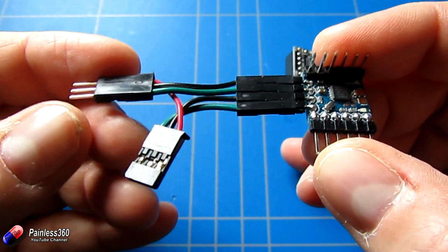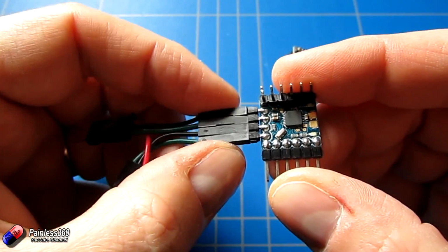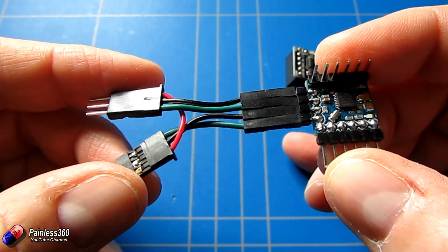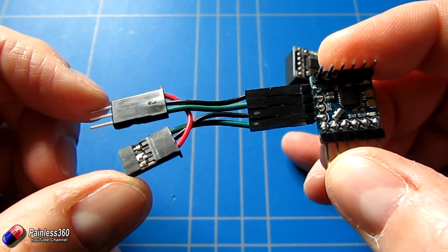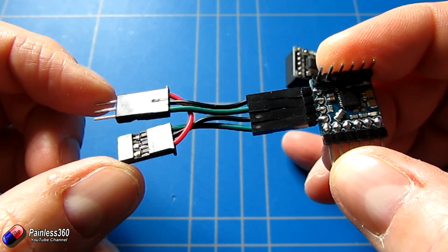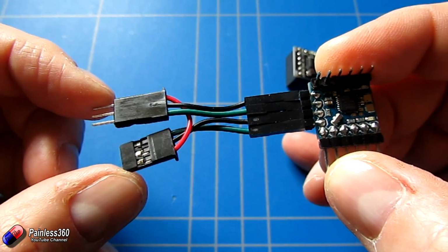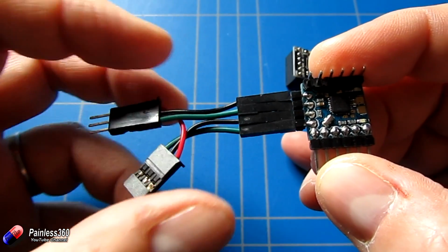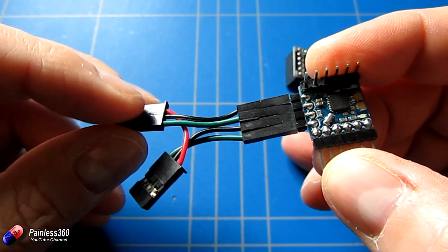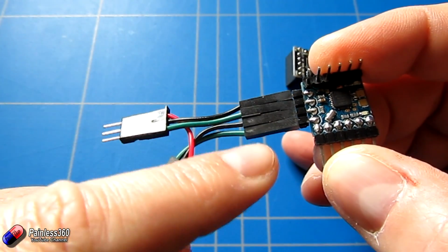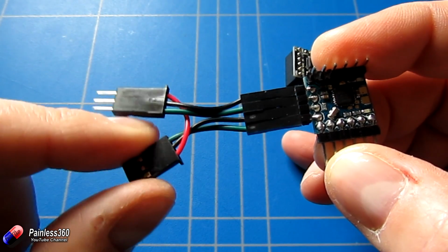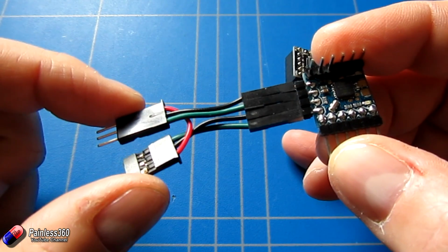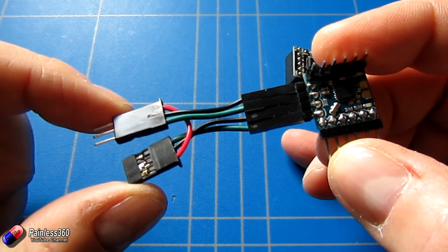The other thing I've done is I've made these pins at the side. These, if you remember, are your video in and your video out, and here's that little red cable that we talked about. Just double check how your camera and video transmitter are wired up, and you can just make whatever adapters you need here. These just happen to be the 2 that work for me. So you can see here we have the ground and the video signal, and we have the ground and the video signal, and then we also have the red cable that's going from one to the other, so that the 5 volts that comes from my video transmitter can just go straight through and out the other side.